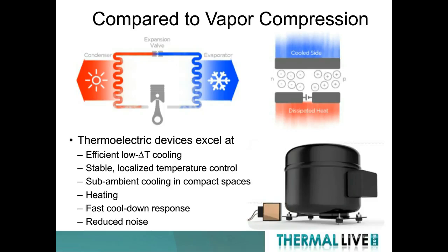Also, vapor compression systems have as a requirement for the function of transporting heat the need for an evaporator and a condenser, an expansion device, and a pumped circuit, which allows it to be remotely located, which is typically a problem. But the secondary heat transport, that pumped circuit, is a different animal with respect to a solid-state system. The thermoelectric elements operate to move heat independently of any other systems being attached to it.